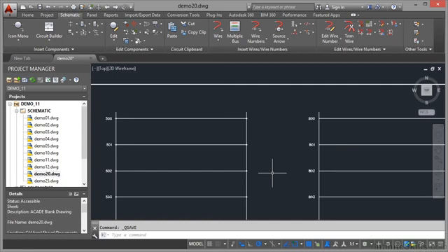When you look at your ladders in your AutoCAD Electrical drawings, you'll notice when I hover over this line here, the properties come up and say it is purely a line on the layer wires. Also here, this line is also just on the layer wires. It's just a line until you actually number those wires using the wire numbering tools.